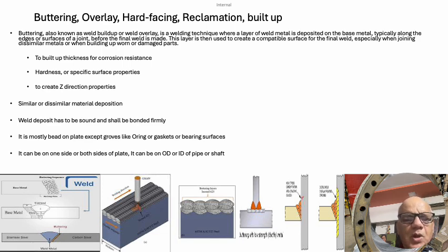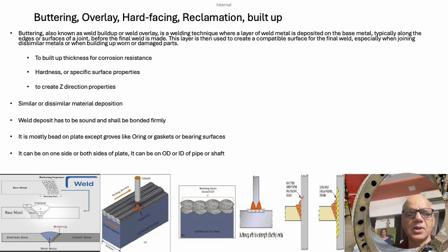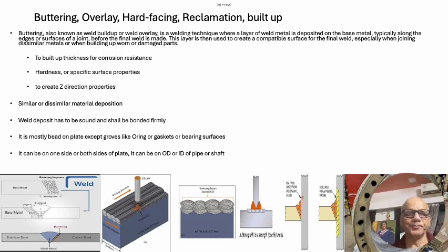So that means we are going to have it on the ID of the nozzles and the entire shell, dish end, and any other surface which is going to come in contact with the corrosive liquid. So that's the way we will be looking at it. And this is, as I said, for building up a thickness which is good to take care of the service life. It may be 1.6 millimeter, 3 millimeter, 5 millimeter, depending upon the service and how aggressive is our corrosion.